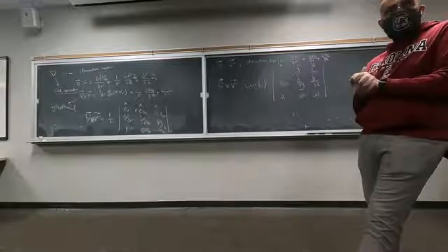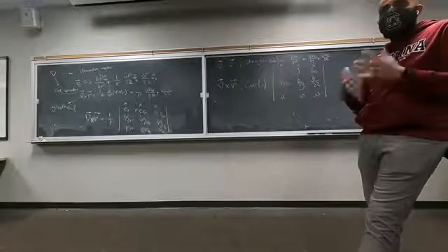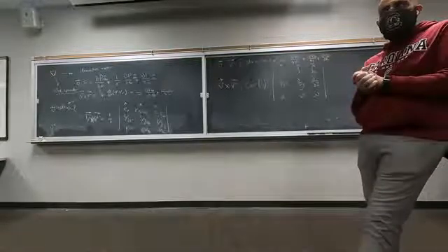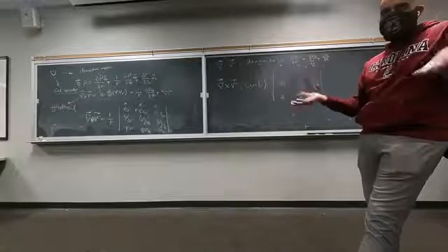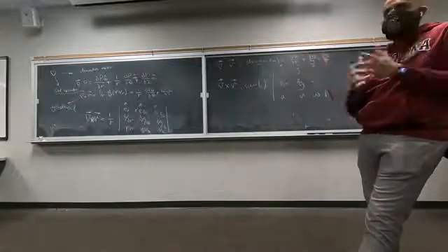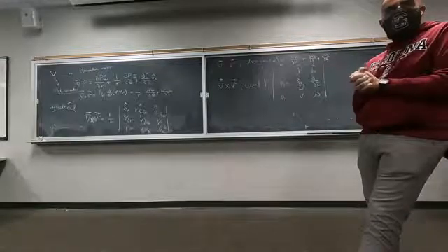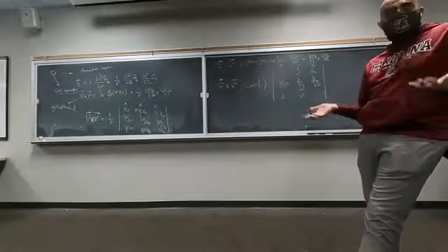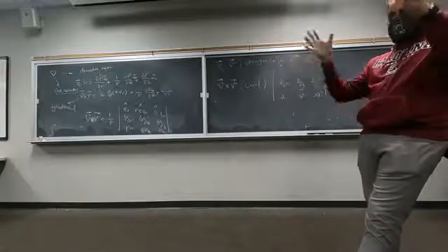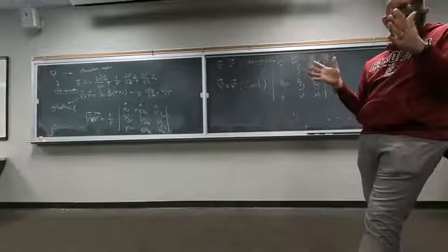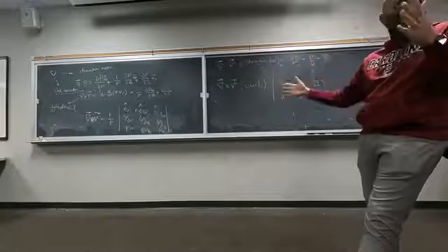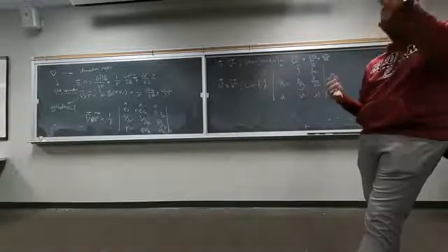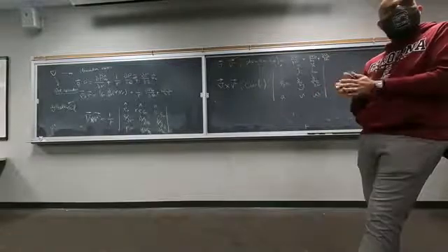The first one is defining a finite control volume. Do we know what a control volume is? Essentially a volume in a space. It can be any volume. It is arbitrary. It can be anything. And then you take that volume, you apply the conservation equations. What does it mean? Conservation of mass. A volume has 8 sides. In each direction, whatever goes in has to come out. Pretty simple. You calculate whatever is going in, which is usually rho AV. A is the cross section of each side. And so on and so forth.